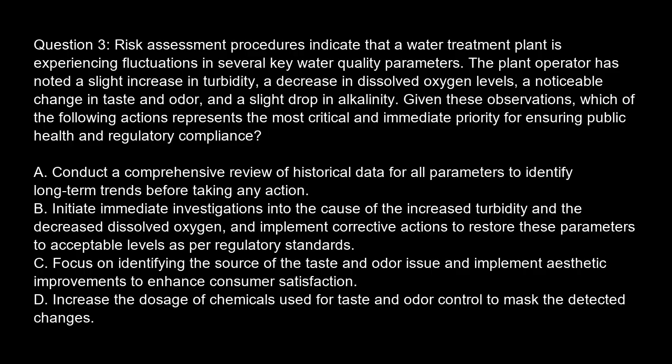regulatory compliance? Option A. Conduct a comprehensive review of historical data for all parameters to identify long-term trends before taking any action. Option B. Initiate immediate investigations into the cause of the increased turbidity and the decreased dissolved oxygen, and implement corrective actions to restore these parameters to acceptable levels as per regulatory standards. Option C. Focus on identifying the source of the taste and odor issue and implement aesthetic improvements to enhance consumer satisfaction. Option D. Increase the dosage of chemicals used for taste and odor control to mask the detected changes.